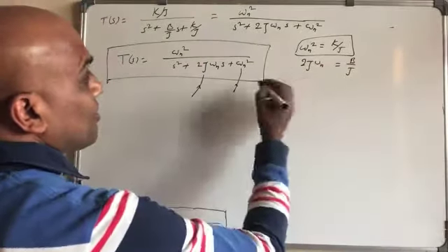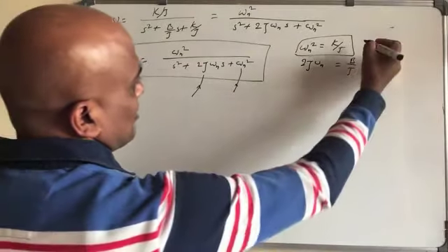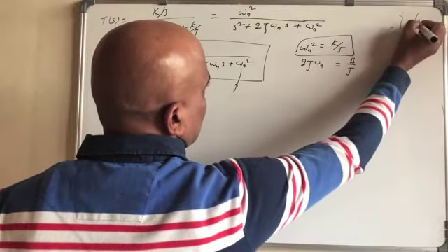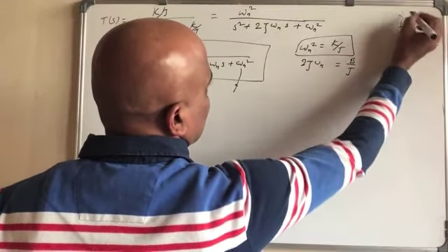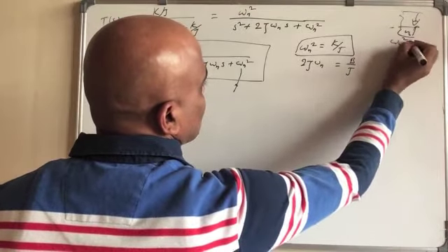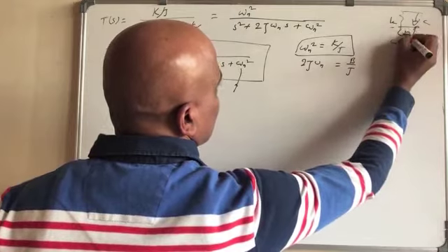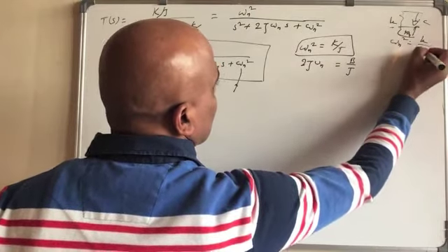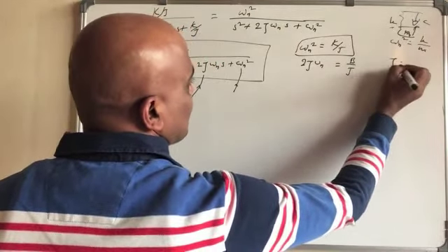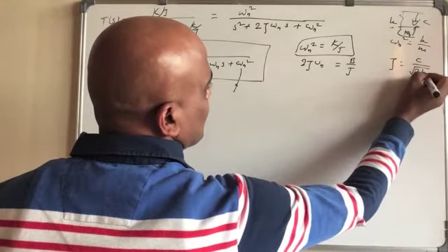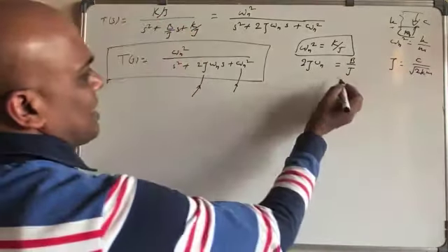So we are getting it from here, right? Okay, so the way we wrote it in a spring mass damper system: we wrote omega n square equal to k over m, and zeta we said c over root 2 km. Similarly, we can write it here.